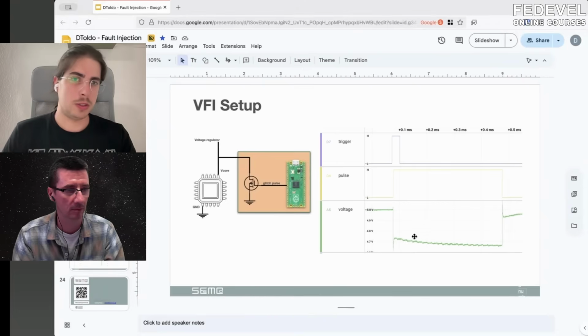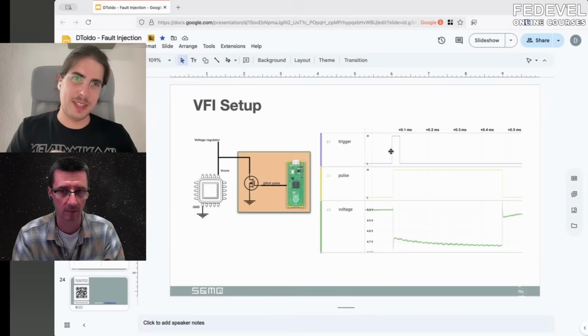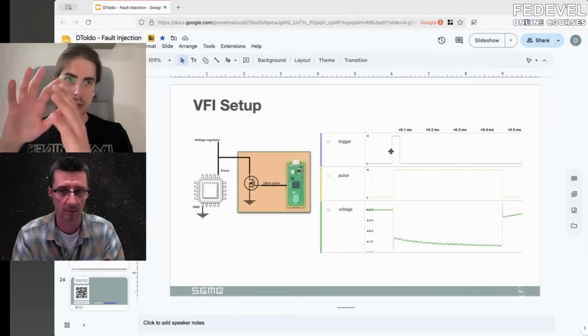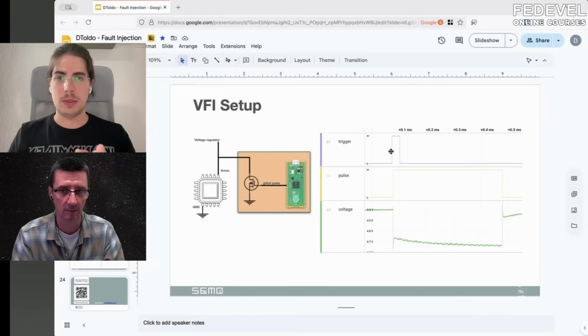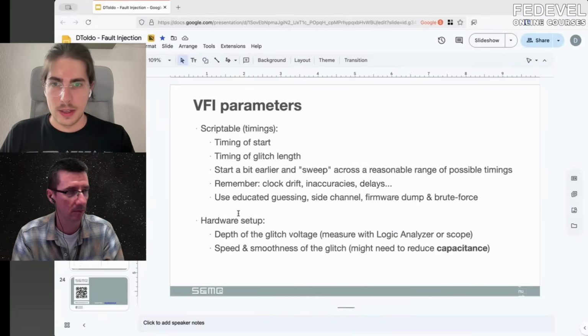And they have analog measurement, which is nice because you could also use a scope which has digital measurements, but I like having both in one tool so that I can have in one interface my digital signals like trigger, reset line. I want to monitor all of this stuff. And at the same time, I want to look at the core voltage, see if something weird is happening or if my glitch is bad. If a wire got loose, you immediately see that the glitch is not perfect anymore. So if anything's imperfect, you can spot it.